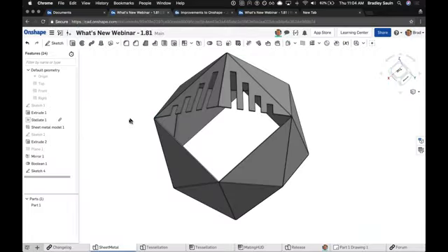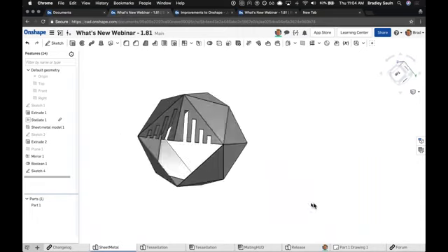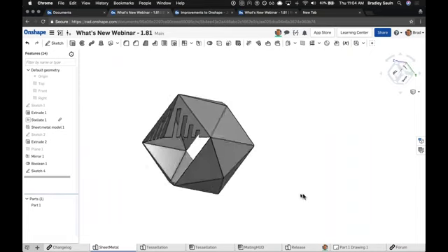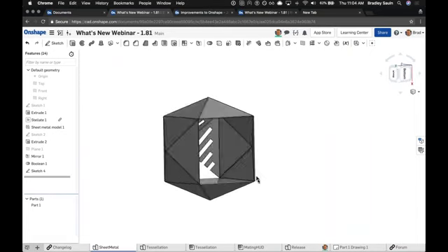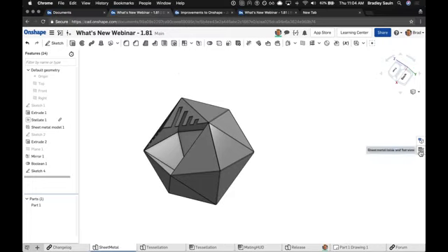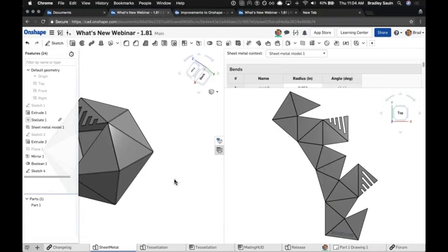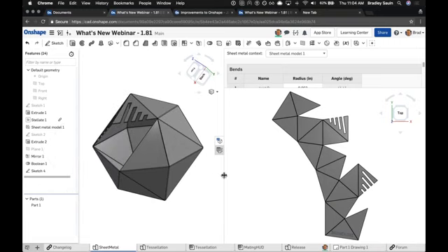Now, going back to the Onshape model, the first one definitely is being able to work in the flat pattern of a sheet metal component. So I made a more complex polygon 3D shape here. When we open up our flat pattern view, we'll be able to see a few things right away about it. I always like Onshape's simultaneous view here, so I can get a nice exact flat pattern right away when I first create my sheet metal part, instead of having to do a lot of flipping back and forth between the design.